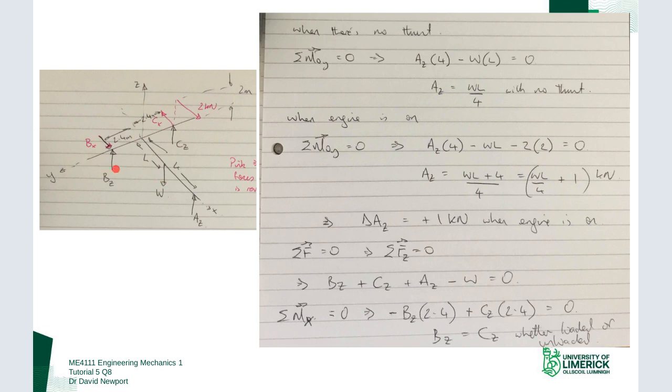So I left my free body diagram in. I'm no longer looking at the picture. This is now what I'm basing my solution off. So I've chosen that y-axis, and I'm taking moments about this axis along here. And the forces that contribute to it are this one here with that distance, W, and this one here, with those distances. So they're the forces that cause a rotation about that axis. You see that this one causes a rotation like that. This one also causes a rotation like that, the weight, and then this one causes a rotation in the opposite direction.